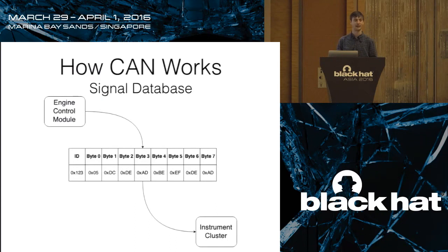Now, when you first connect to a CAN bus, you're going to see data flying around, a lot of these all over the place. And what's actually happening in your vehicle is decoding. So it's quite simple. The bytes of this message will have meaning, which is predefined at the time where the vehicle software was designed. So in this case, these first 2 bytes might be an engine RPM. I actually saw a CAN bus just the other day that it was in fact a message, not that ID, but it was the first 2 bytes for an engine RPM, just direct correlation.